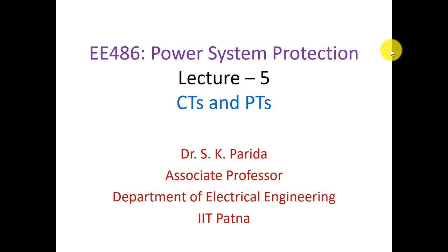So in this class we'll see, because CT and PT are transformers, what happens when there is a DC offset current because of the switching phenomena in the transmission line. Because of that, the core of the CT and PT saturates very quickly. Therefore, it is very important that before the CT gets saturated, the relay should operate. And if it does not, then the relay will maloperate.